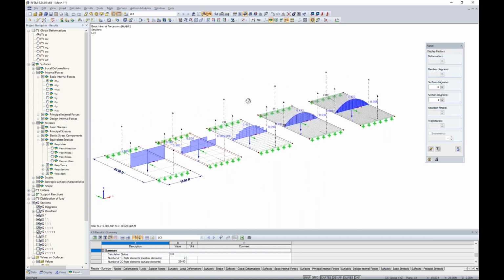Now, how do we check this for our own structure? Well, we can just manually refine the mesh, run the calculation, and take a look at our results. Let's rerun the calculation with a more refined mesh. Are our results drastically changing? If yes, then we need to continue refining until we get to a point where the results are not changing much, and then we can probably move forward with our static analysis.